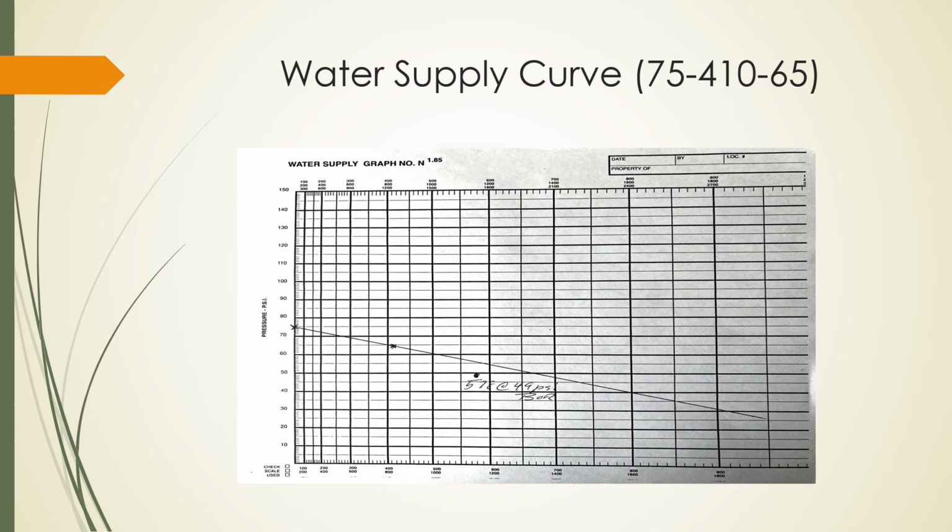And then I just threw in a number here from one of the prior matrices that we had used to calculate a sprinkler system. We had 578 GPM required at 49 PSI at the base of the riser. So you can see that point sits below the curve, which indicates that we have adequate water for the sprinkler system. Once I start doing the hydraulic systems, I'm going to get into some pretty interesting stuff with supply system curves and start to play around with them and show you how to extrapolate numbers from them. It's going to get pretty interesting.